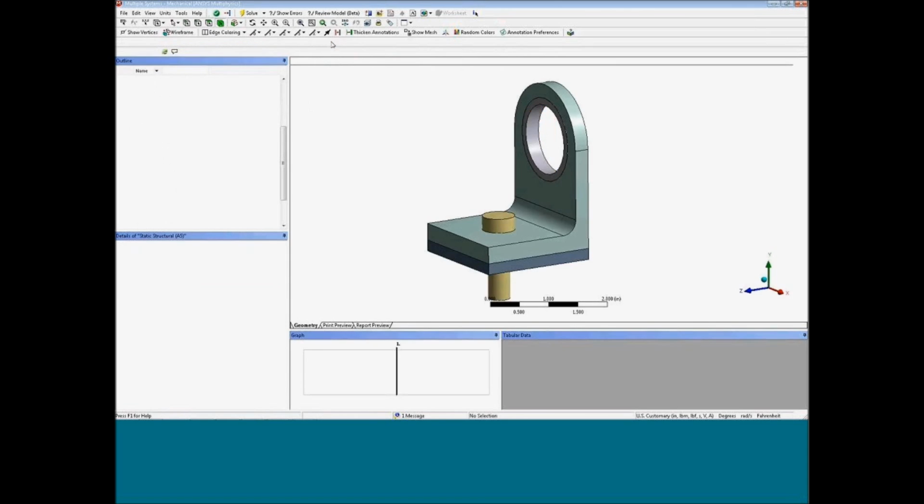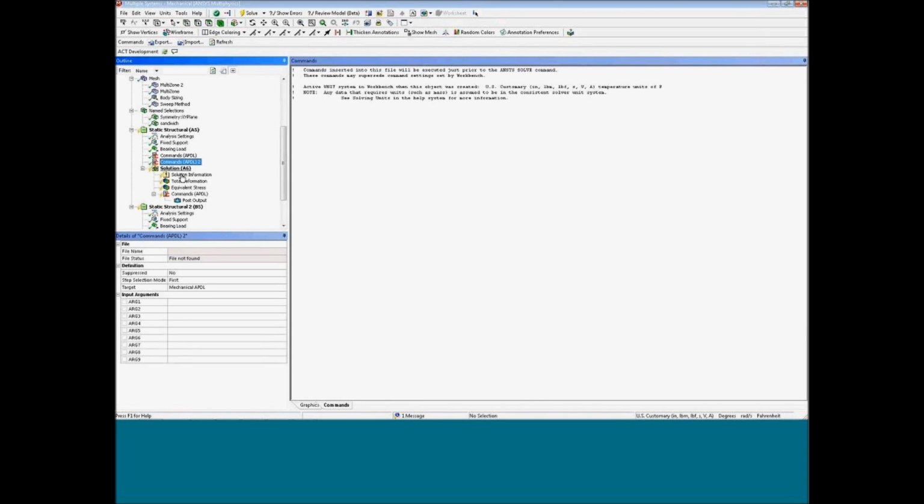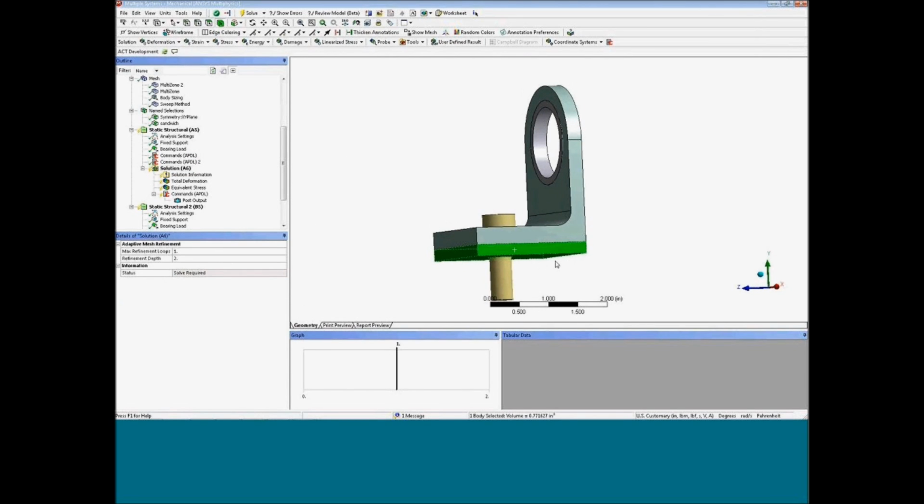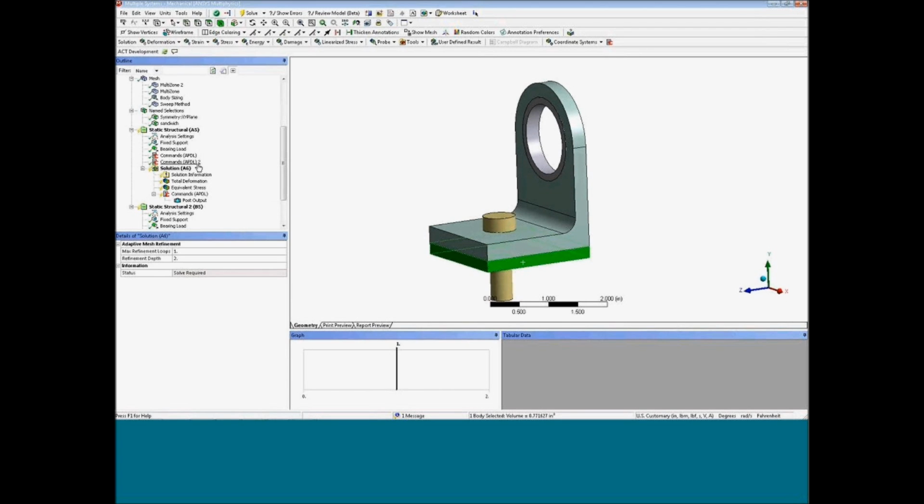So if I insert a second command block in here, maybe I want all the commands that are inserted in this command block to be executed on a certain load step. Maybe I'll say load step 2 in this case. So load step 2, what I'm going to do is maybe I just grab those composite elements and kill them, or remove the stiffness from the simulation in the second step. So this would do that. So we run the first analysis with this command block, get the results, and then the second step, maybe the properties have degraded, or whatever you're doing, you want to get rid of that for some reason. We do that on the second step.